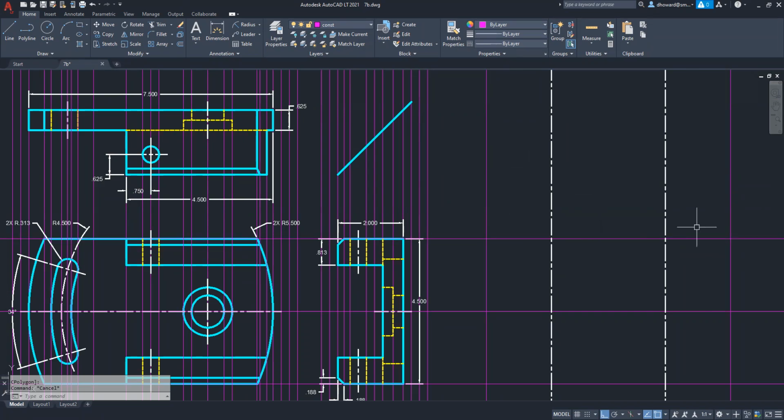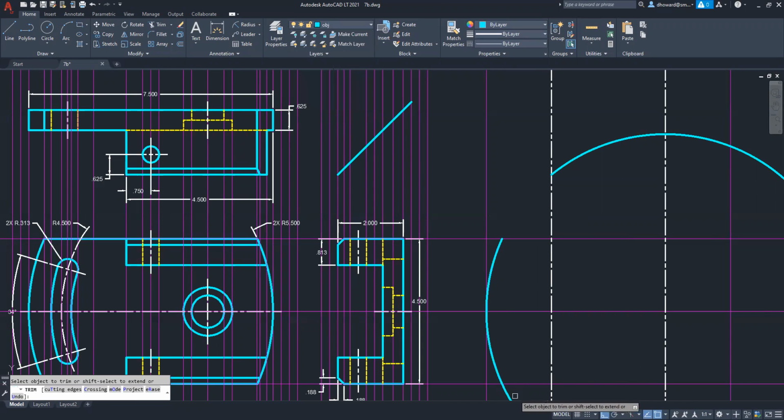At this point, I'd like to just do the basic outline. To do the basic outline, I need the arcs. I'm going to go to my object layer, and I could use the arc command. You know, we never do that. We always use the circle command and then trim, which I like doing a lot. For example, here it is, clicking with the circle command and just going to the edge and then trimming off. That's it. And then just delete what you don't want. It's pretty simple doing it that way.